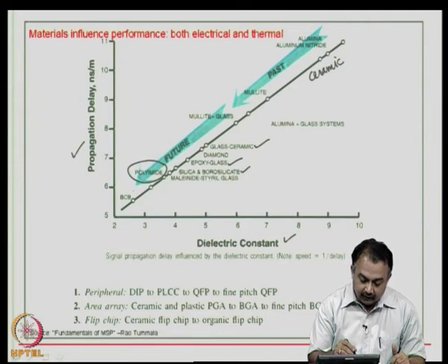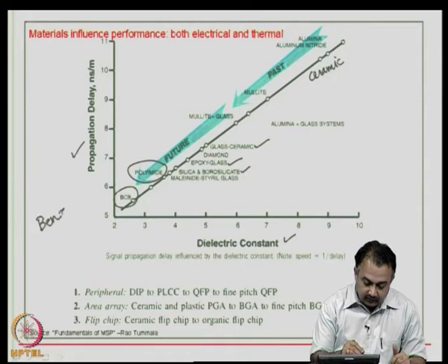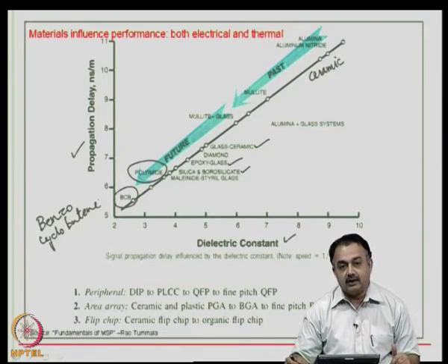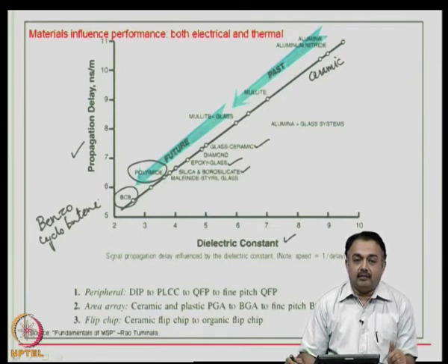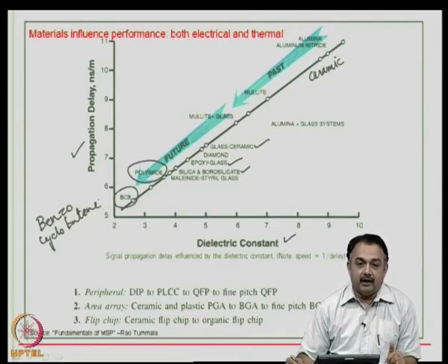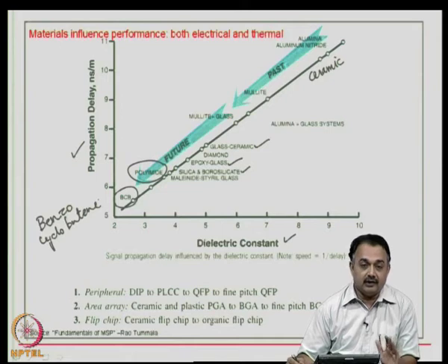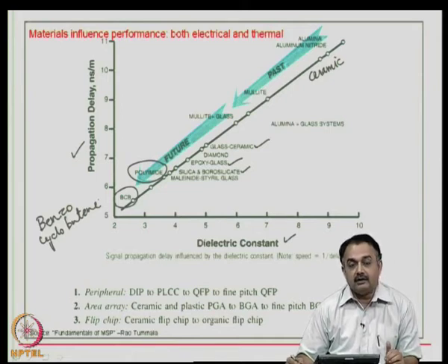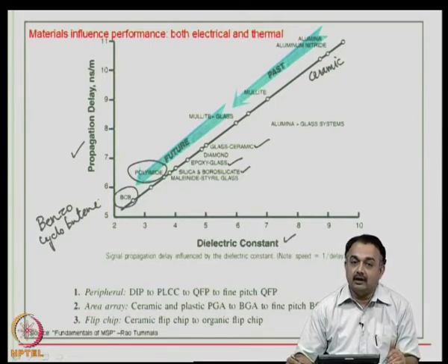Another material that is being used today in semiconductor manufacturing is BCB. BCB is benzocyclobutene, whose dielectric constant is close to 2, and therefore, you can expect much better electrical performance. Electrical parasitics could be very low if you are thinking of using it as a very thin dielectric in manufacturing. Here dielectric material choices could relate to the substrate, could relate to thin dielectric layers used in the buildup of these package substrates, and it also could mean encapsulation.